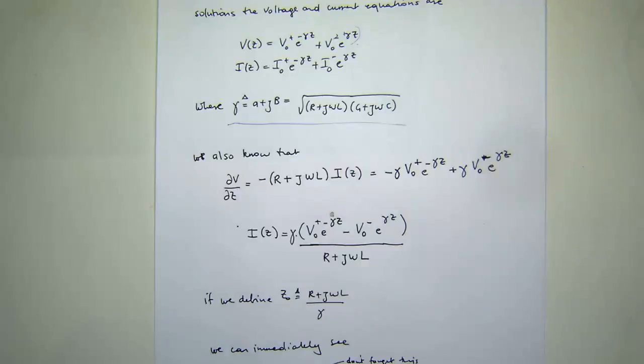Perfect. So if I'm saying that a transmission line is lossless, essentially what I'm saying to you, if you had an exam question or you were trying to make an approximation for a lossless transmission line, is that R and G are 0. Now, in reality, that never exists, but in some cases it's a good enough approximation.